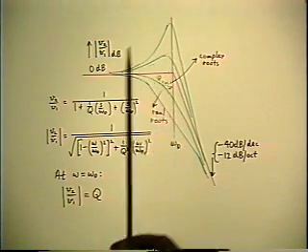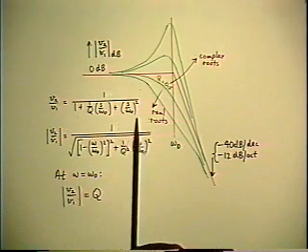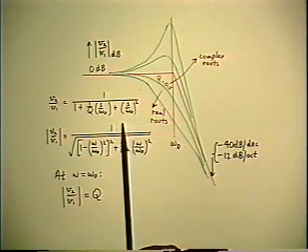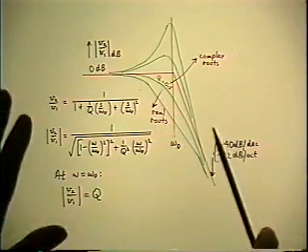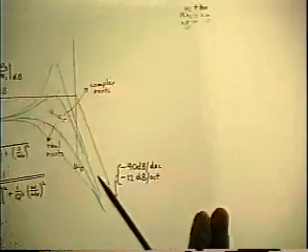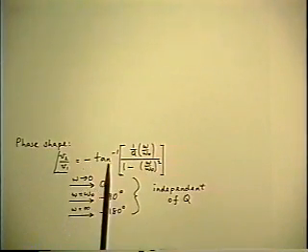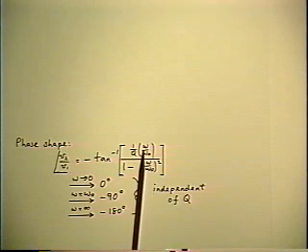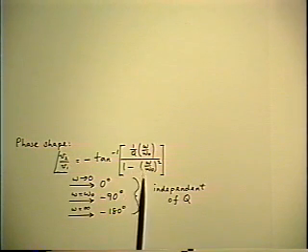Okay, this is the standard handbook version of the generalized second order response in terms of Q factor. And of course, you want to know what the phase graph does at the same time. So let's construct that. The phase is again minus the arctangent of the ratio of the imaginary part of the quadratic to the real part. A little more complicated this time.